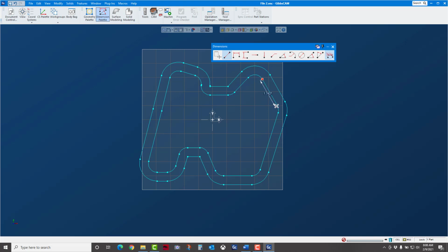dimension. And if I really want to keep it there, I can hold the control key down and select them both. Same thing with horizontal here. If I go here, see, I can just hover my mouse. And if I want to commit, I would hold my control key down and pick the second point. If I do that, see, it's going to stay. Let's go to horizontal, vertical, that's all standard stuff. Point, angle, okay. Radius, circle, but there's a couple new angle ones.